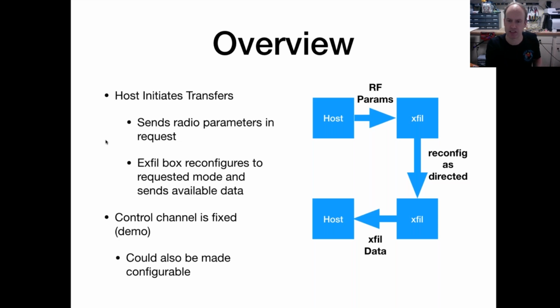There's a bunch of different things the host could be, but essentially it's a computer with an SDR hanging off of it. And that computer has some amount of code on it that will transfer to the exfil box inside the target location a set of RF parameters saying, hey, go ahead and reconfigure yourself to use a particular frequency, a particular type of modulation, a particular type of encoding. Go ahead and reconfigure yourself based on what I'm telling you. That exfil box is going to receive that transmission. It's going to say, okay, I'm going to change myself to be a different kind of radio.